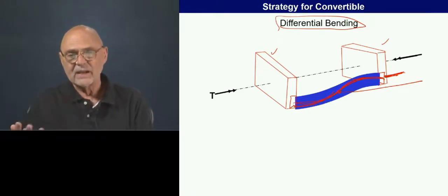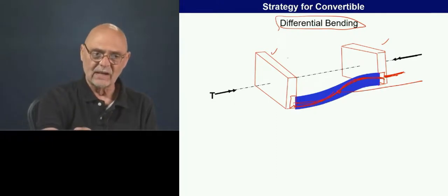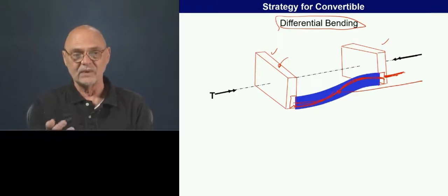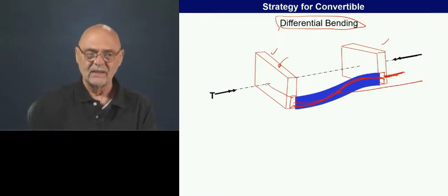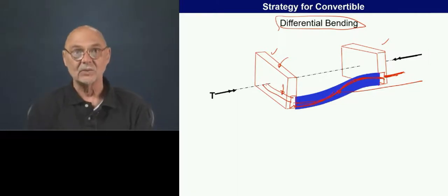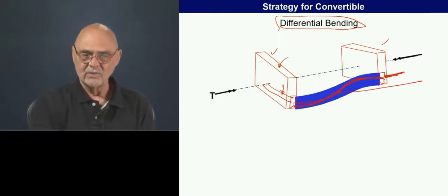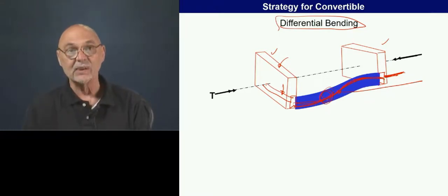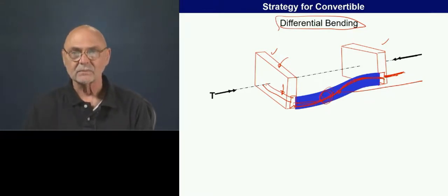So how would you analyze this? You analyze this essentially as a rigid structure that geometrically translates the rotation right to the rocker, and then we would analyze the rocker as a beam in bending, and we got the tools for that earlier in the course.